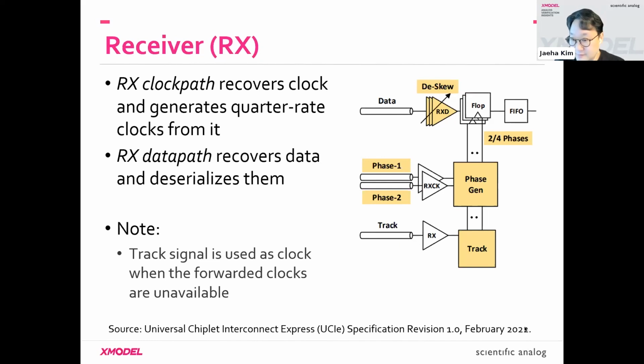And the last question from Vic is, you want to mix Cadence schematic blocks along with the system level blocks. So it really depends on what you mean by the Cadence schematic blocks. If the Cadence schematic blocks are circuit schematics, the real circuit schematics, then you have to use the Cadence AMS, which supports the mixed mode simulation, like the co-simulation between SPICE and Verilog.